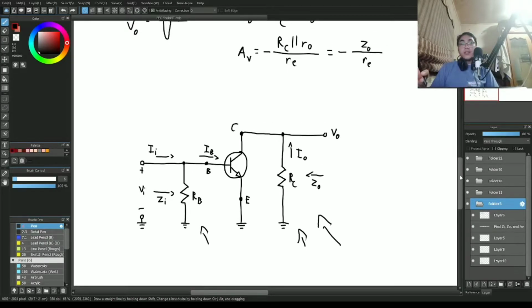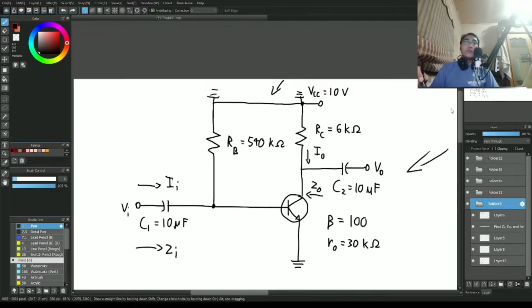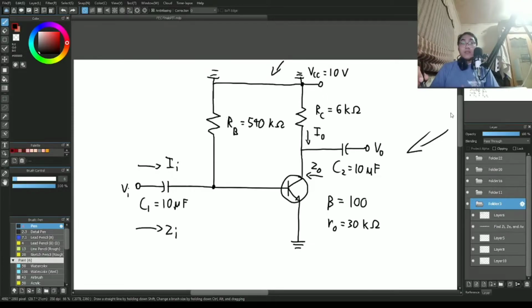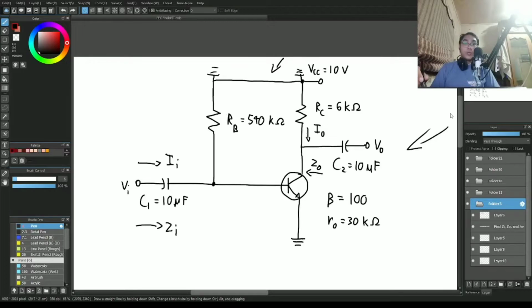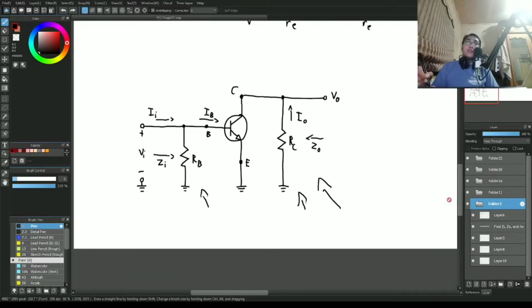It's because in AC analysis, small signal analysis, we must assume that the DC voltage, not a DC source, is 0. Because of that, that means it's an open circuit. So because of this right here, once VCC is gone, it grounds this part here and this part here. Hence, why in this new model, it's like this.